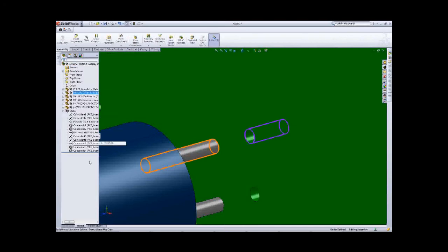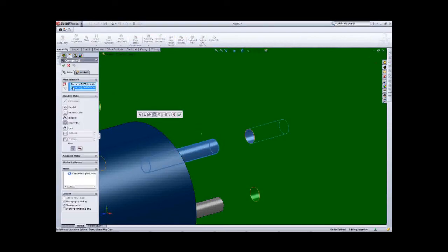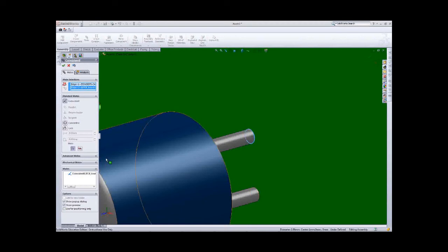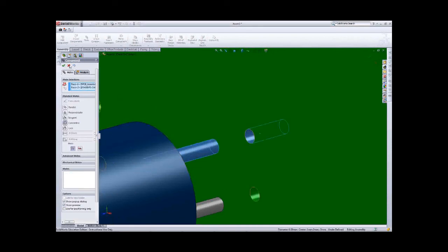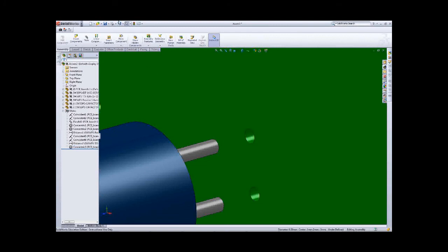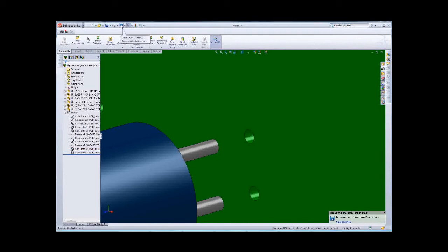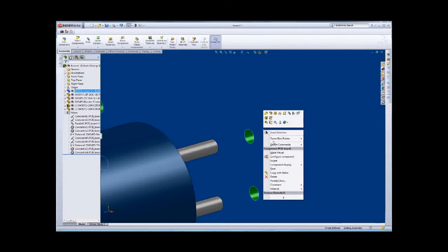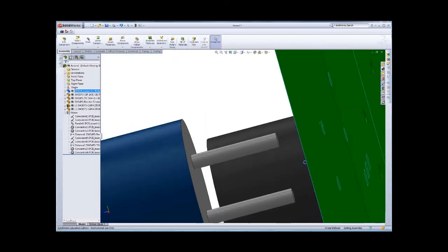the concentric. But if I delete that mate using edge to edge, you can use the coincidence here. So I think we can use different ways to mate it together, but I think that one you can use face to face to make the concentric, and then using face again to fix it, because we can use that one face